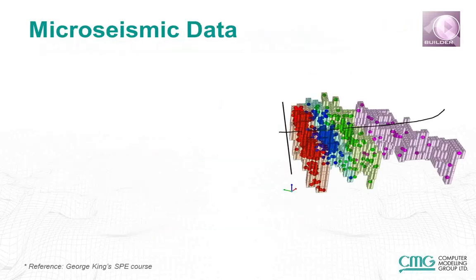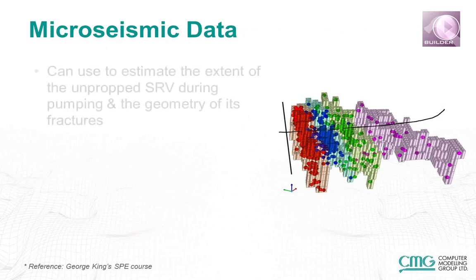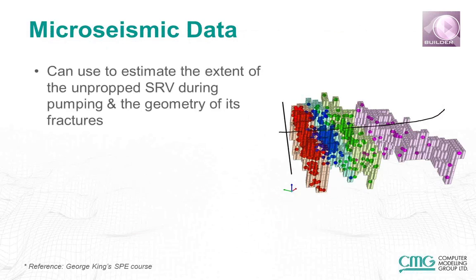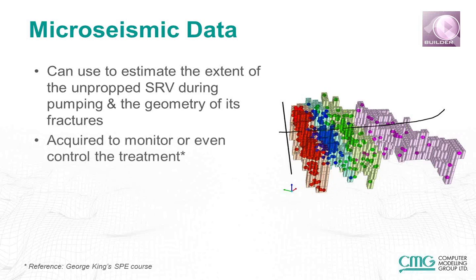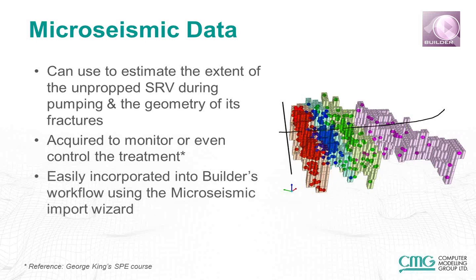One other thing that we've added in a few years ago is the ability to incorporate microseismic data into your simulation model building. Often this information is captured during the stimulation process, which can then be used to estimate the extent of the unpropped SRV during pumping, as well as the geometry of the fractures that will be generated. During treatment, this is often required to monitor or even control the treatment, and we can easily incorporate this information into Builder's workflow using the Microseismic import wizard.